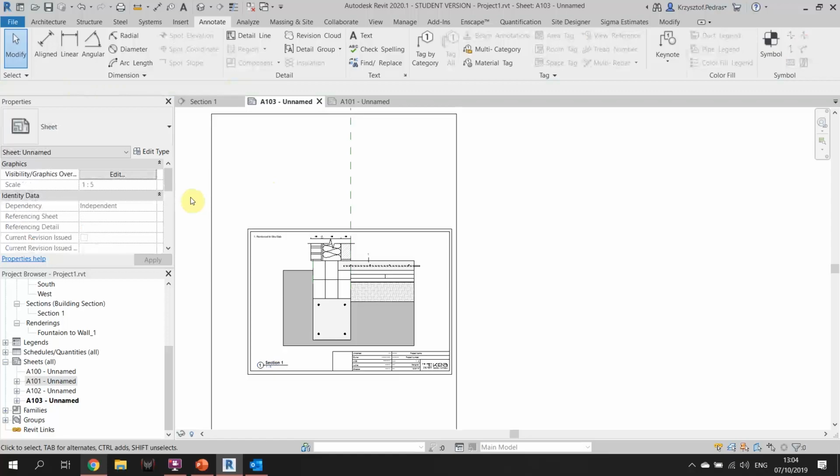Because sometimes the drawing is quite complex and you want to annotate everything, a text which would take this much of the drawing is not very practical, right? If you have like 50 elements, then the text would just not fit. So you use numbers and put them out in a list. It's the same principle: try to keep the annotations aligned somewhere, either around the object or on the side, so they just don't go all over the place.